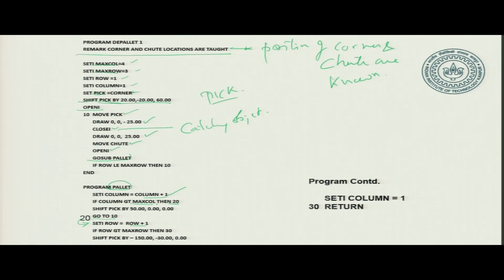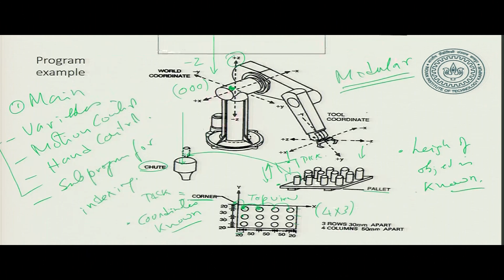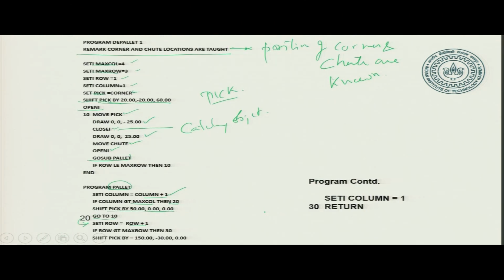Now, if the column is not exceeding, then it will shift pick by 50 0 0. If you go back here, you see the pick point was here, so it shifted by 50, it has come to the next object now. Okay. So, this is 50 0 0, so it has come to the top of the next object. So, this has been picked. I want to go to the next object now, I am coming here now. Okay. So, that is what the indexing program does. Now, after doing this, it will go to 10. So, go to 10 means it will go back here to 10.